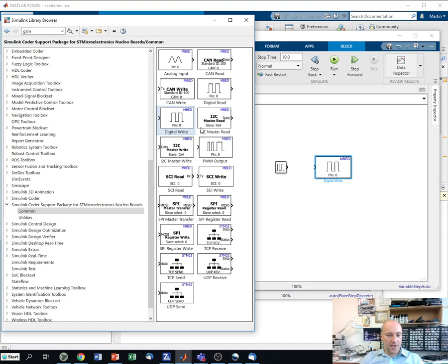Here is I2C. I2C is a serial bus typically used to communicate between integrated circuits. You can read data from an accelerometer, from a gyroscope, from a pressure sensor, but the point of I2C is that it's on the board and it communicates over short distances, a few centimeters, 10 or 15 centimeters at max.